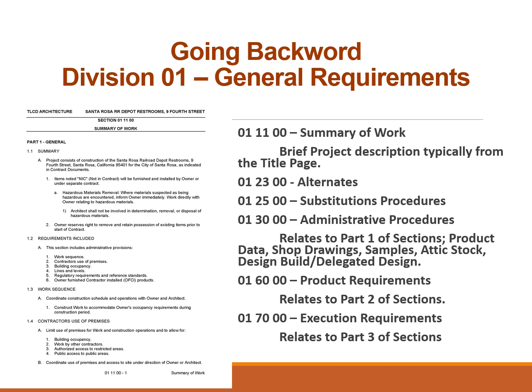The next thing you have to worry about, once you're reading all this: all the things about finding materials should be in Parts 1, 2, and 3 of the technical sections. But when you start getting into specific requirements, especially those that are general throughout the project, now you go back to Division 1. So Division 01, General Requirements, might just as well be at the end of the documents as at the beginning, because technically in most of these situations you're going to want to read the section before you actually go back and ask, do they have something relative? Example, the experience of the